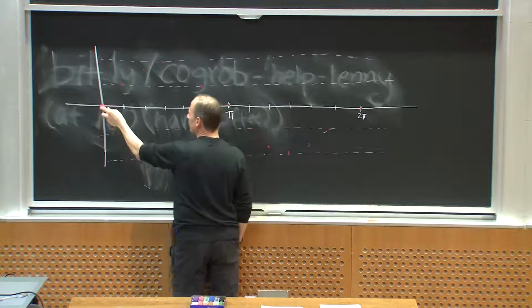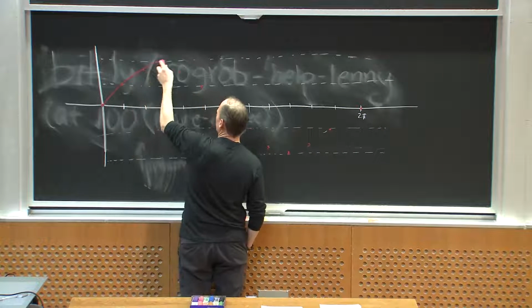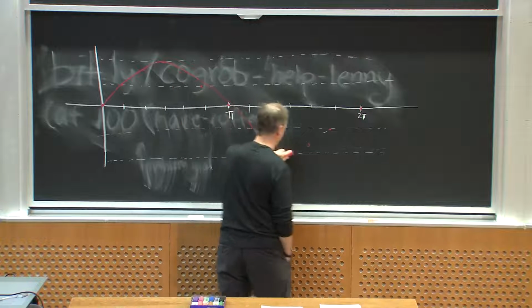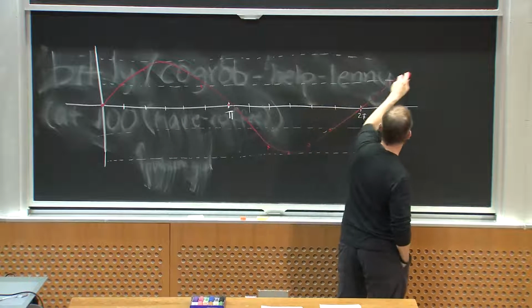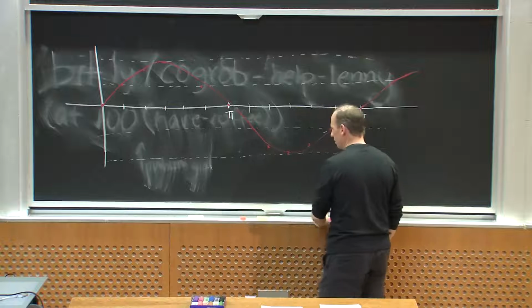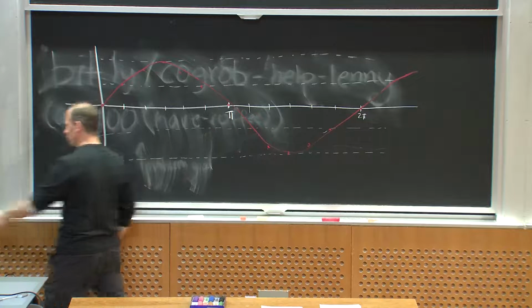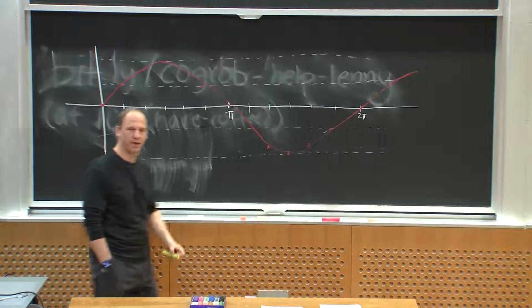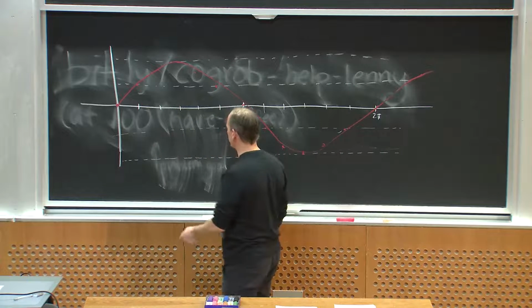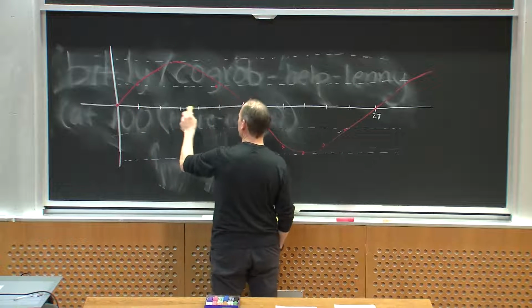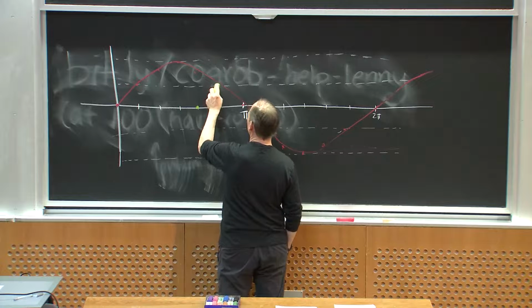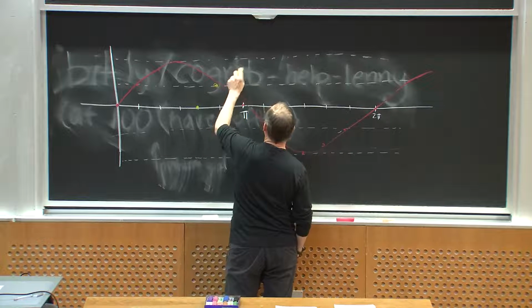And here's the pain of dealing with three-phase systems, you've got lots of waveforms to plot. Okay, VB would just be VA lagged by 120 degrees, or 4 pi over 6, 1, 2, 3, 4 units here. So it would be doing something like this.